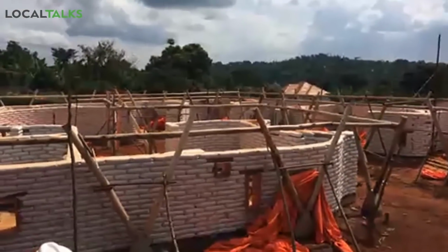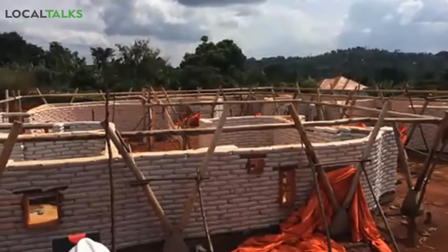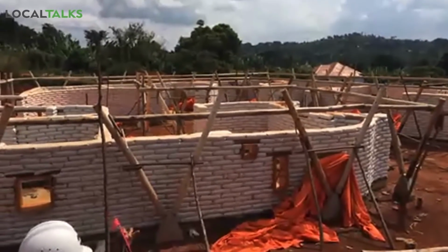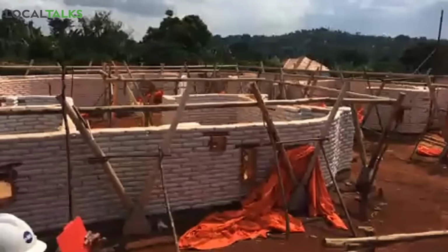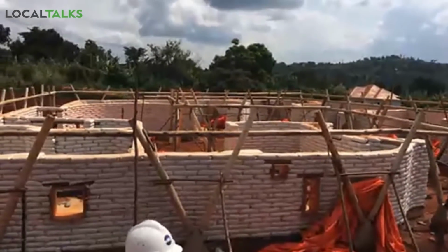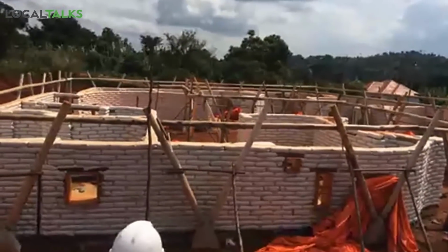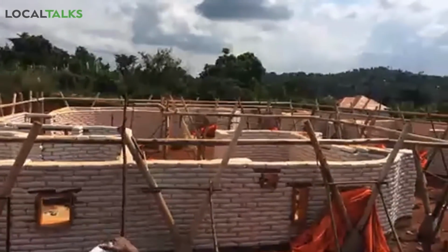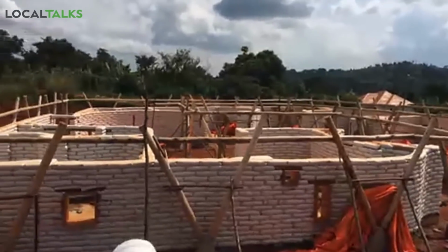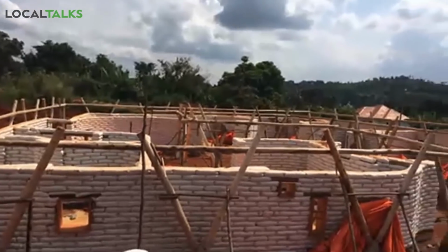While we are here, maybe it is also important to briefly talk about the columns and the V shape of the columns. I think we had already explained that the roof itself is not actually supported by the walls. The walls do not touch the roof. It is the columns that do the majority of the work. Only some of the partition walls, those walls that are essentially separating the classrooms, will go all the way up, but not in earthbag.